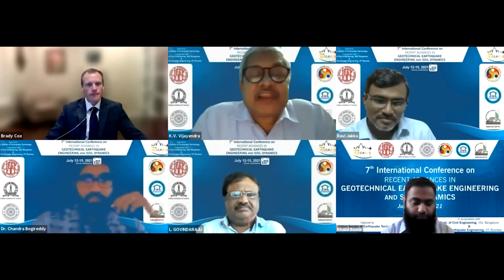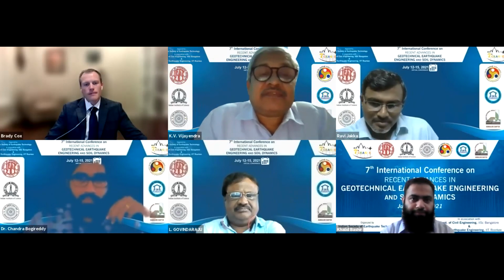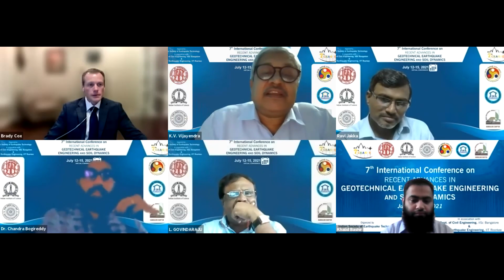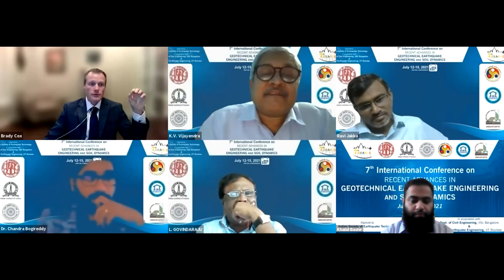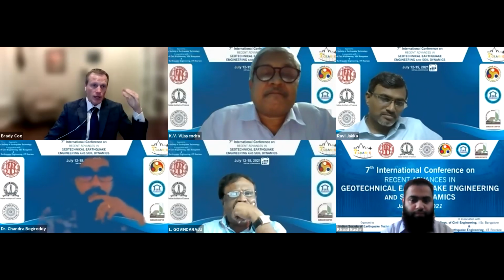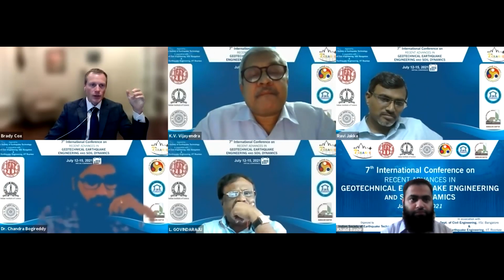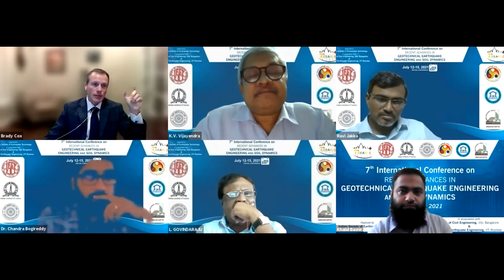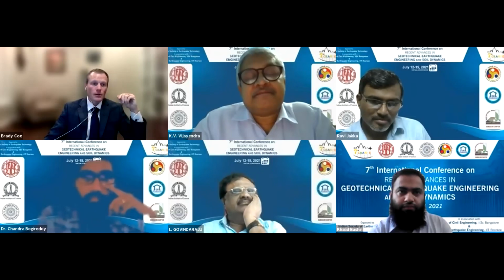Thank you. One last question, Professor Cox. In the shear wave velocity profile which you adopted to get the transfer function, what was the minimum damping ratio used? Was it from Stokes and Darendeli? Yes, that's correct. When we did our normal 1D site response analyses without modifying damping, we used d-min from Stokes and Darendeli, and it varied as a function of material type and confining pressure. But d-min would have typically been on the order of 1% to 2%, depending on whether it was clay or sand. And when we modified damping using Rathje's approach, we would take that d-min and multiply it by a factor of 3 or a factor of 6 in order to bring down the amplitude of the fundamental mode peak.